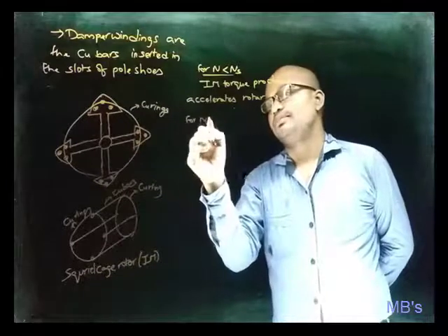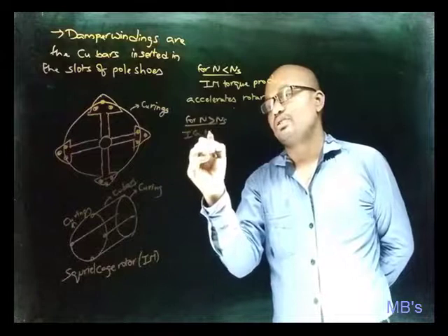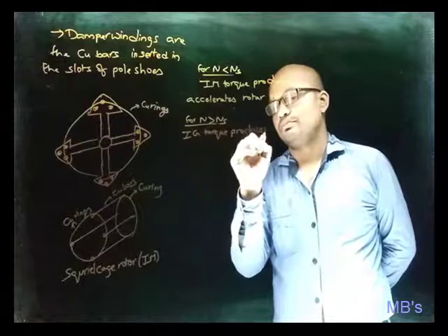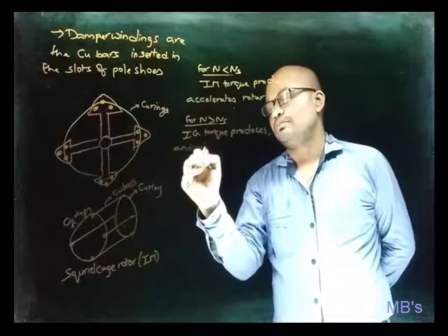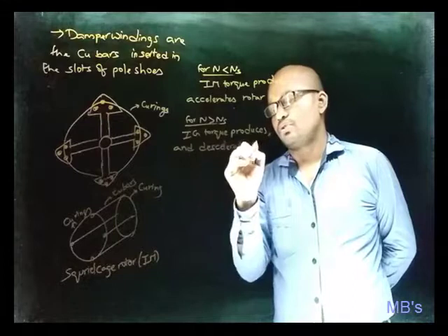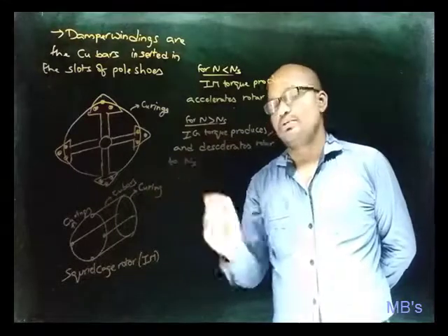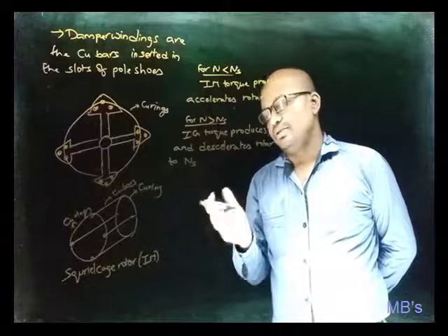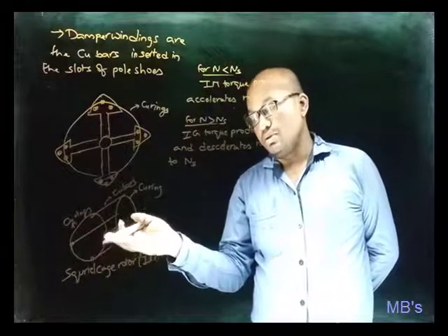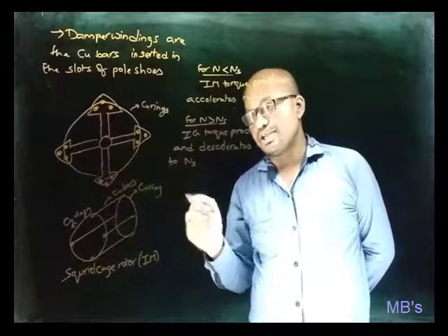And for speed greater than synchronous speed, induction generator torque is produced and decelerates the rotor to synchronous speed, and upon reaching the synchronous speed, the induced EMF in the damper winding will be 0, so that the machine will run as it is in normal operating conditions.